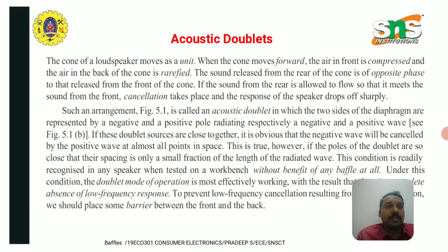If these doublet sources are close together, it is obvious that the negative wave will be cancelled by the positive wave at almost all points in space. This is true, however, only if the poles of the doublet are so close that their spacing is only a small fraction of the length of the radiated wave. This condition is readily recognized in any speaker when tested on a workbench without the benefit of any baffle unit.